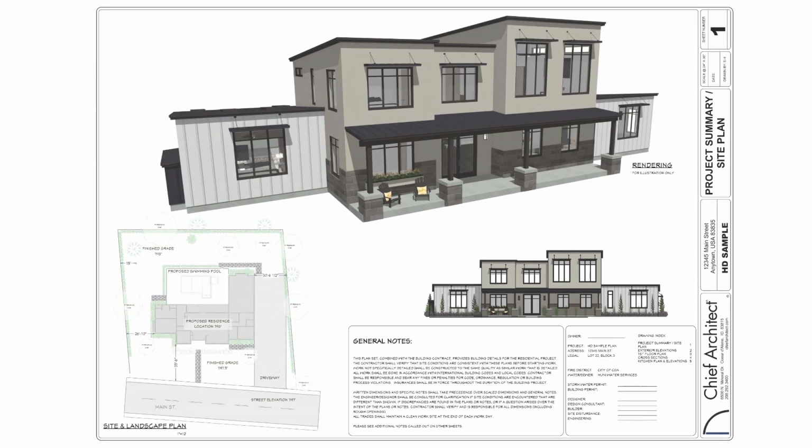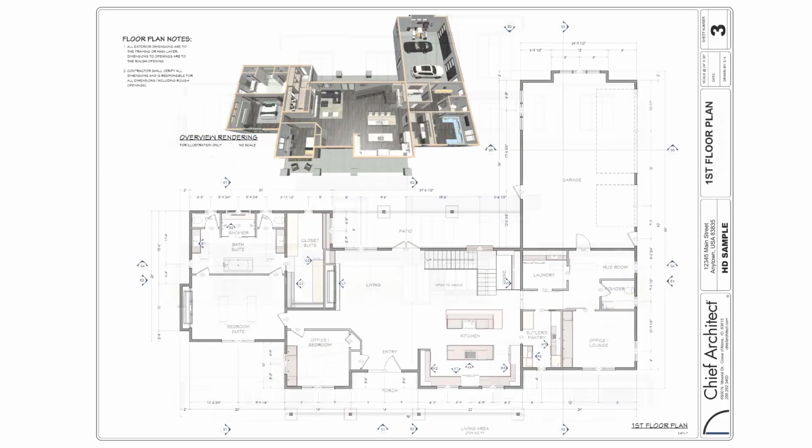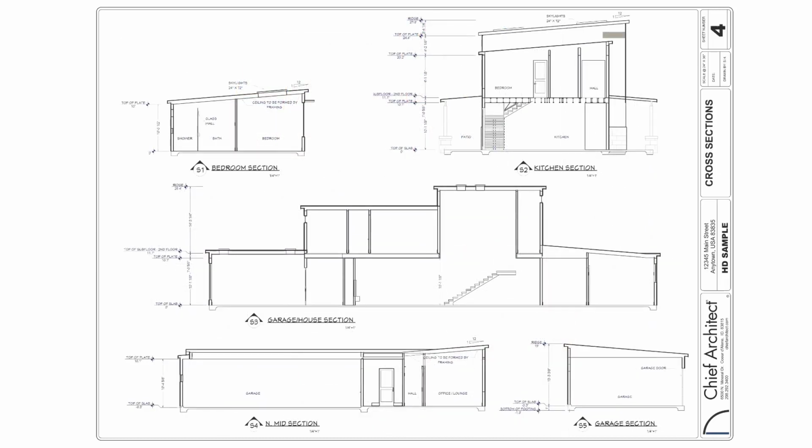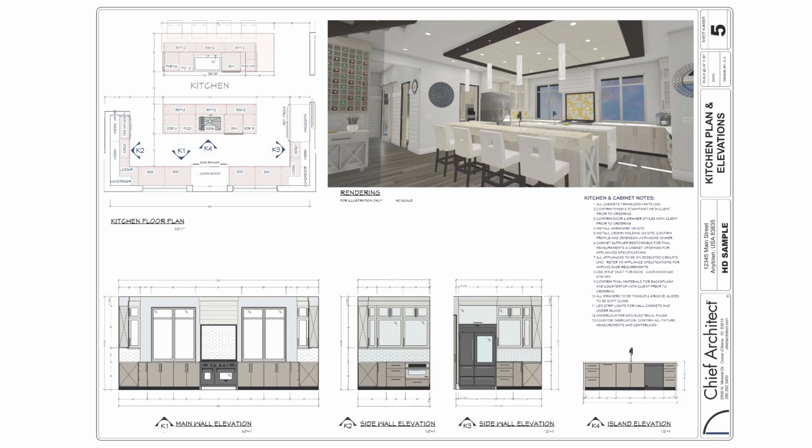With Home Designer Pro, you can create scaled construction drawings that can be used for building permits or construction. Any view you have in your plan can be sent to a layout sheet where you can define its scale and organize your drawings, floor plans, elevations, and sections. Individual layers can be turned on and off to create just the view you need for your layout documents.